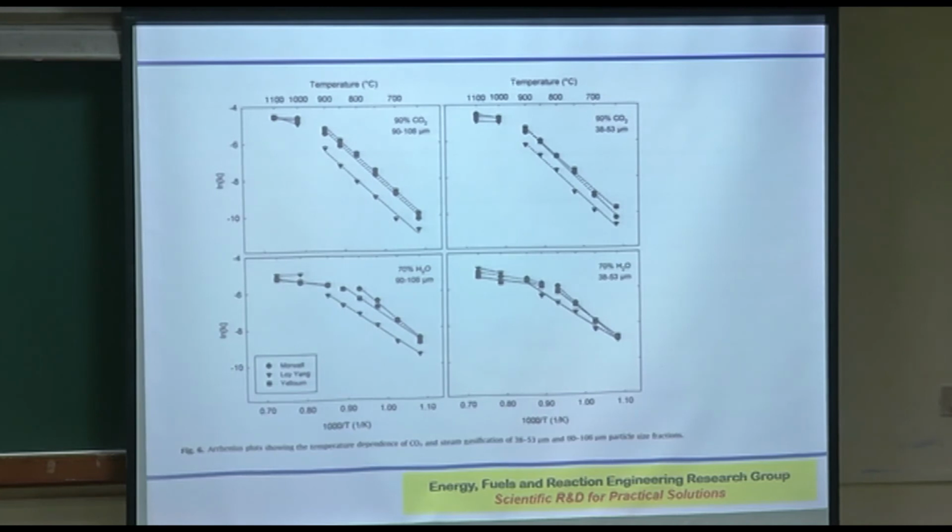So there are 3 distinctly different zones that you can see, which correspond to the chemical reaction rate controlling zone; the left side, which is definitely external diffusion controlling; and somewhere in between is the blank zone, pore diffusion control. So those are the 3 zones that you have.